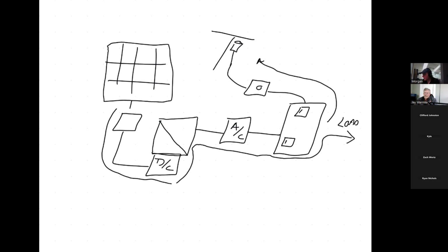Obviously, a tiny fraction, but it lowers the voltage. And when I turn off that light, the voltage is raised slightly until supply and demand compensate. So as I add more demand, the water pressure or the voltage goes down. As I reduce demand or I increase supply, the water pressure increases or the voltage increases, and we have a range of plus or minus 3% or 5% or 6%. Okay? That's how they modulate in the short term.